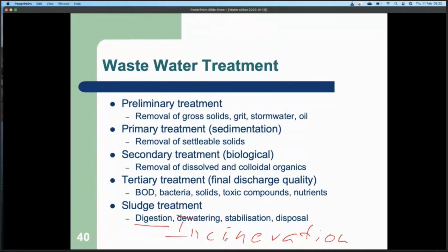And I say incineration here rather than energy recovery because it's not really about the energy. I know that's the technical, the correct word. But the important thing with incineration is the high temperature. You need to get really high temperature so that all these man-made substances, the pesticides and inhibiting substances, stuff that affects biological functions, need to be destroyed, and you destroy them by using high thermal conditions. So why not call it incineration? But that's just my point. Anyway, the big thing that was missing here was incineration, and there we have it now. Good. So that's in a nutshell what happens in wastewater treatment.